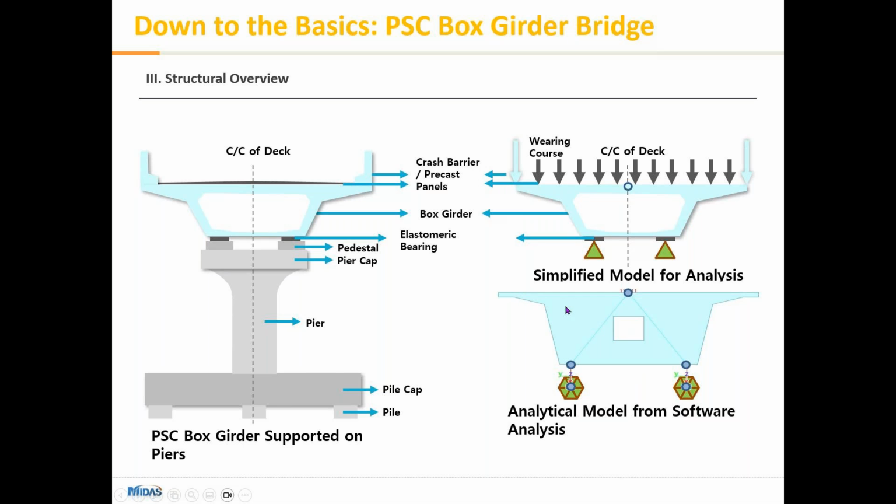In the 3D geometry, you could see this particular cross section of my box girder, and the whole box girder will be modeled as a single line element, which will be my beam or frame element, which will have 6 degrees of freedom on both sides, as I am considering a modeling in which I will be using the center top approach. So what is the center top approach?